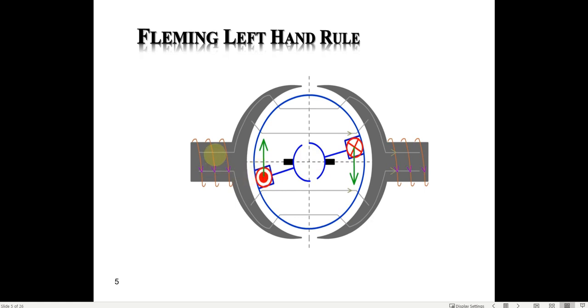And then there is a field current which is going here. It sets up a horizontal magnetic field out here. And then the motion is in the vertical axis. This is the y-axis, the field is in the x-axis, and the current is in the z-axis, moving into the screen and out. Because of the field in the x-axis and the current coming and going into the screen here, this experiences an upward force, and this experiences a downward force.